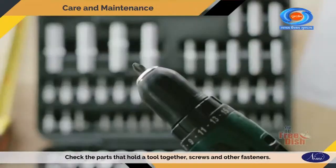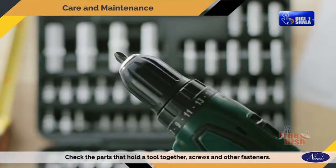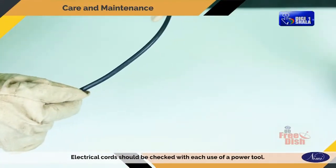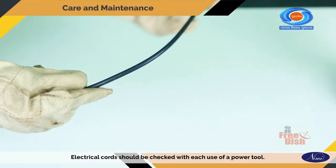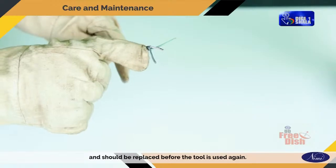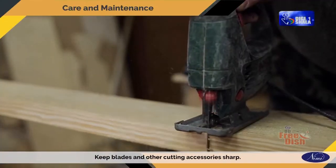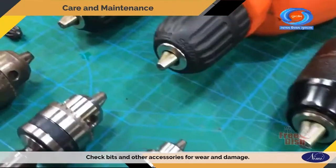Check the parts that hold a tool together, screws and other fasteners. Tighten up anything that might have been shaken loose during operation. Electrical cords should be checked with each use of a power tool. A bad power cord can be dangerous and should be replaced before the tool is used again. Keep blades and other cutting accessories sharp. Check bits and other accessories for wear and damage.